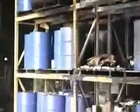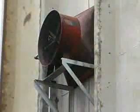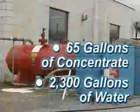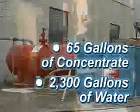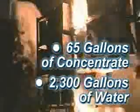Saving any product is a great achievement with an intense fire like this, but the key success of this test was that the fire was immediately contained and the high-expansion foam prevented the fire from spreading beyond the rack to other areas of the facility. The high-expansion system used only 65 gallons of foam concentrate and 2,300 gallons of water in 8 minutes of continuous discharge. The test was determined to be highly successful by all parties involved.